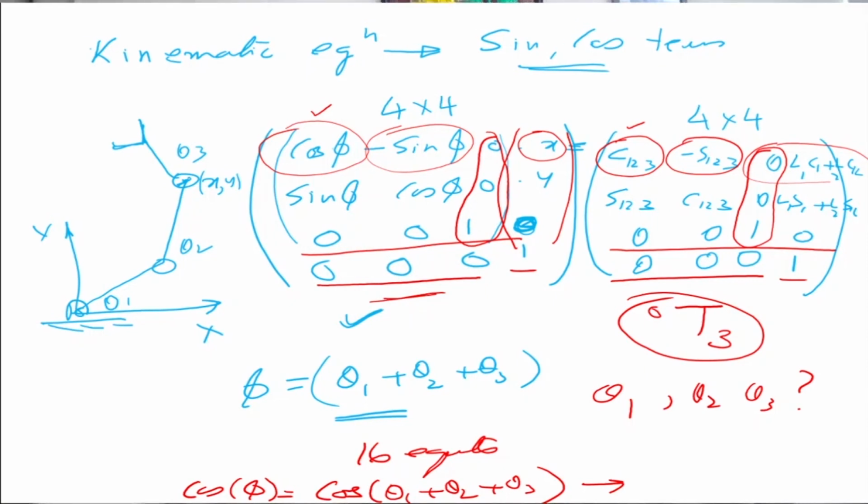What I would suggest is that please go through the DH parameter assignment. The frame assignment is extremely interesting, and it's not only interesting, but it's important. If you cannot get your DH parameters right, then you cannot do inverse kinematics anyway. For large manipulators it's not very easy, but once you systematically assign the frames, it's easy to get your DH parameter table and then your transformation matrices, and from there you can get the relationship between the last frame and the zeroth frame.